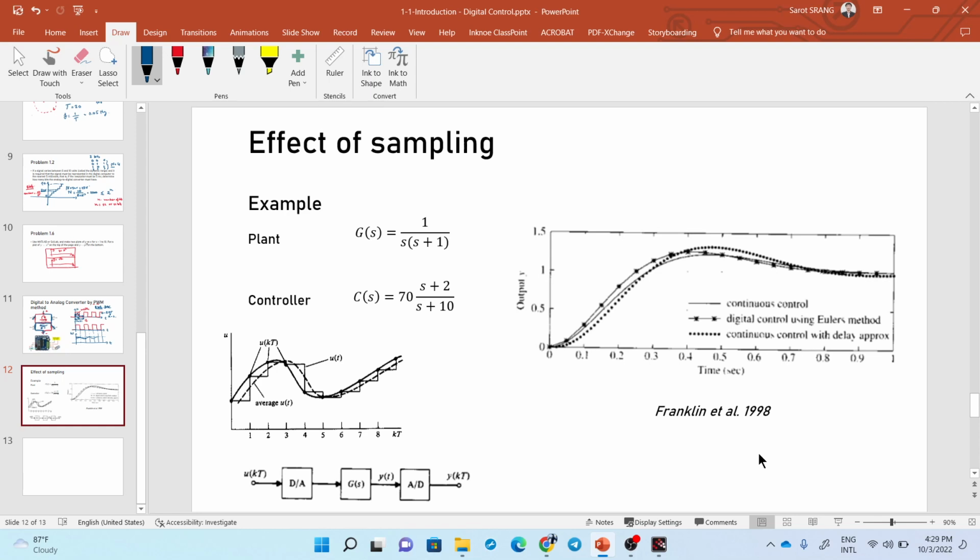Actually, there are two things to consider. First, the numerical method applied on the discretized system is itself just an approximation to solve the differential equation. There are many ways to solve differential equations. If you model as continuous in MATLAB or Scilab, it will pick a numerical method that computes very accurately and can represent the continuous solution.